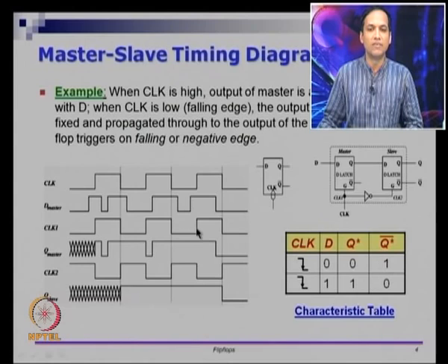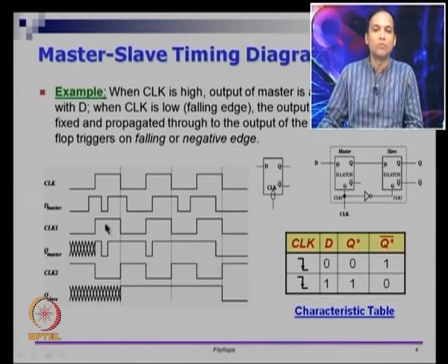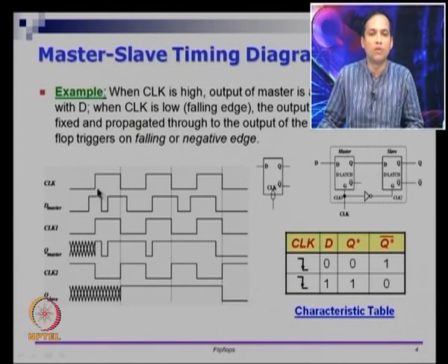And finally, when the third clock tick comes on, at that point D master is already 1, it goes down to 0 once, and that is captured in Q master, right. If you notice, we just traced the relationship between the external clock, D master and Q master. If you compare D master and Q master, you can see that not all the transitions in D master are transferred to Q master, right. A subset of the transitions are actually left out.